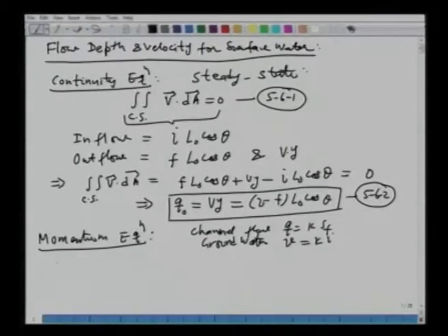Now, in this particular case, we have the sheet flow or overland flow, which is uniform in nature. So, for the uniform laminar flow, let us assume that the sheet flow is laminar for right now, and for the turbulent case, we will consider it later. For the uniform laminar overland flow, we will take the momentum equation from our knowledge of fluid mechanics.